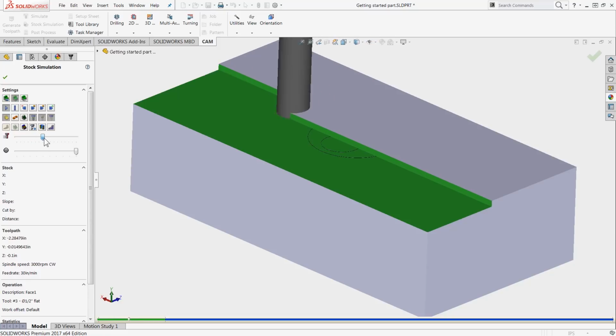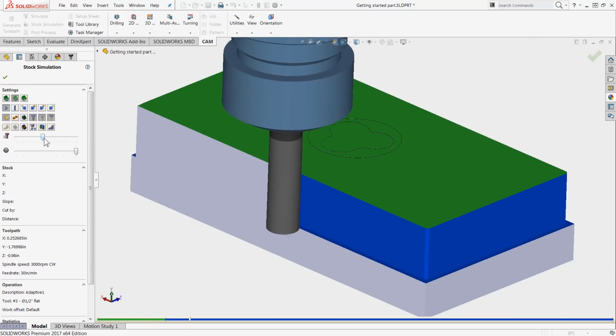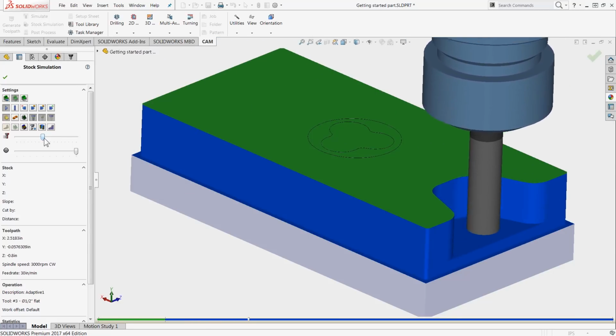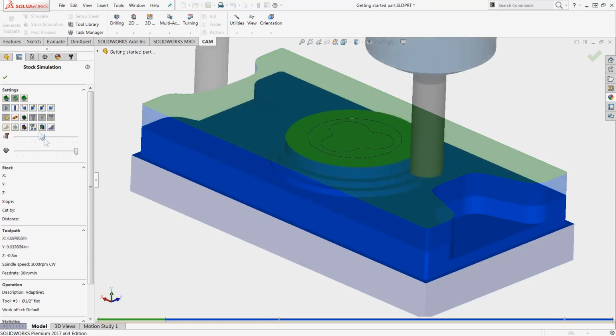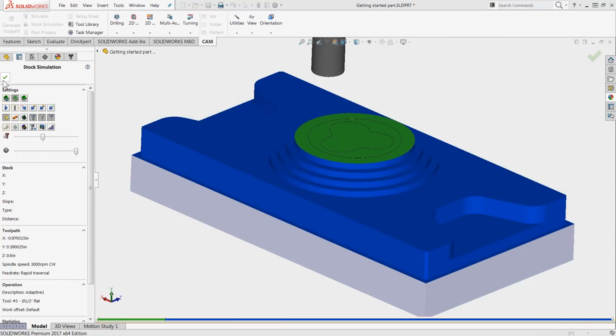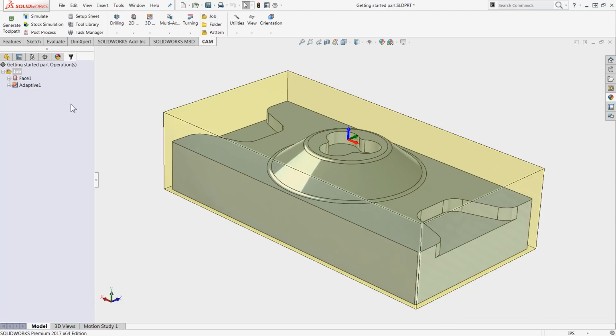After our facing operation, you will see the adaptive toolpath utilizing a constant load on the cutter, making sure our cutter is going to last a lot longer. You will notice that the adaptive only removes stock where the cutter will fit. The clover pocket at the top was left alone because we need a smaller cutter. For this, let's explore the 2D adaptive toolpath.